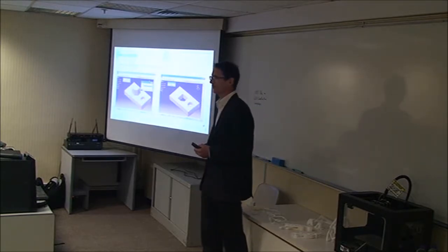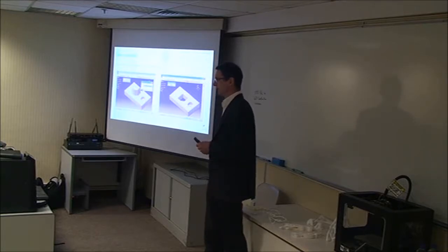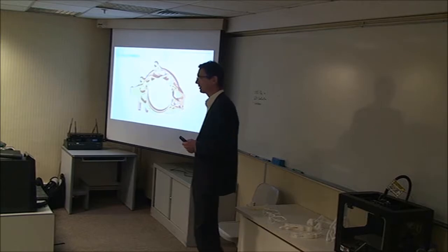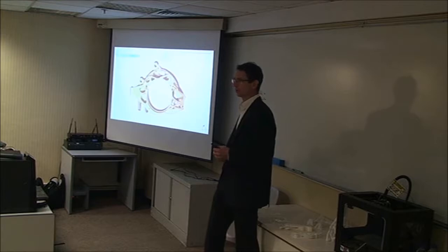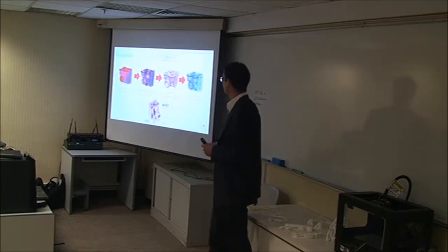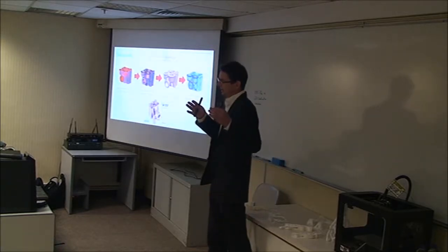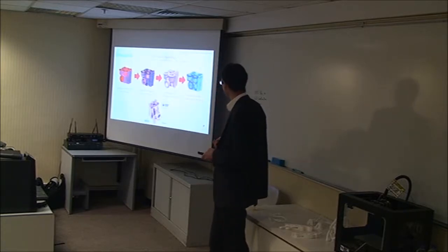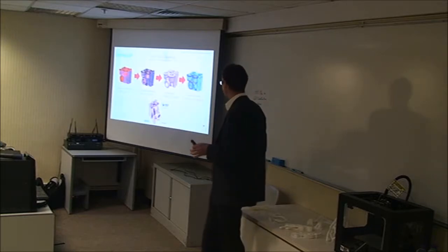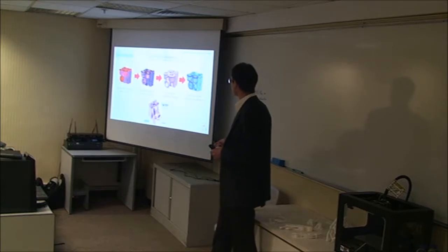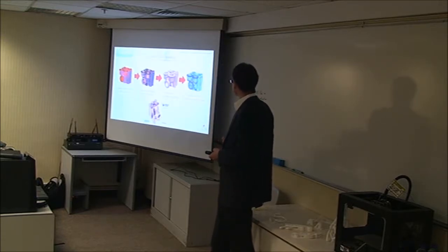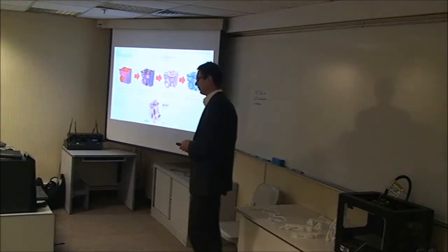The traditional CAD, conventional CAD, is based on Boolean rules and steps, and it is more or less the same as you produce parts. And when you want to bring that into a CAD design, then you're frustrated because it's not going to work. And the best way is you don't use any CAD. You directly go from these shapes that the optimization methods generate into a direct geometric representation, an STL model, for example, and you skip all this CAD stuff. And the valve block, an example here from the optimization using a smooth functionality, and later on you directly get an STL model, and you can print it as it was optimized in OptiStruct.